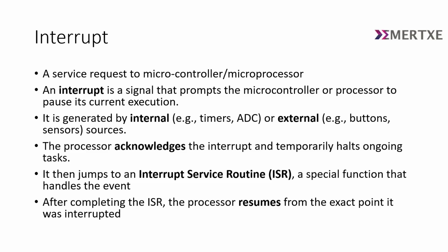The processor acknowledges the interrupt and temporarily halts ongoing tasks. It then jumps to an interrupt service routine, a special function that handles the event. After completing the ISR, the processor resumes from the exact point it was interrupted.